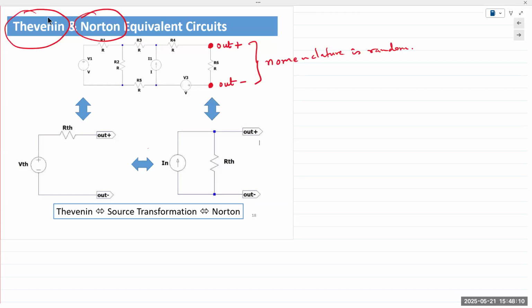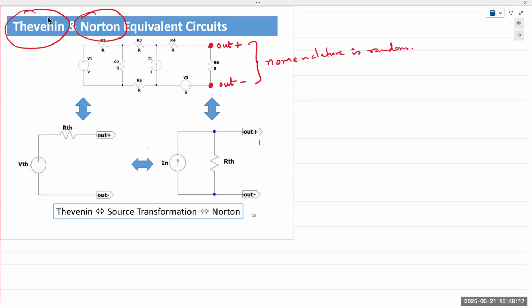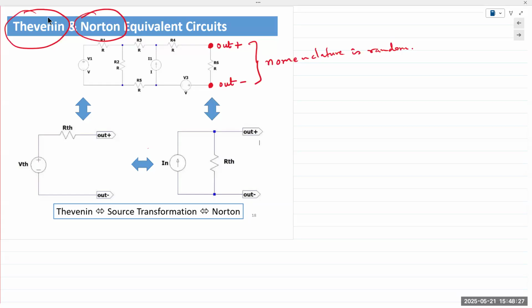The professor, whoever the instructor is, is going to simply say, okay, remove the capacitor, find the Thevenin circuit of that voltage source and this resistance. And you need to be able to do that within a few minutes. You won't be tested on this separately, but as an electrical engineer, when you're performing circuit analysis, you need to be able to quickly and efficiently reduce a circuit down to its Thevenin or Norton equivalent. That's how you would encounter this in future courses.